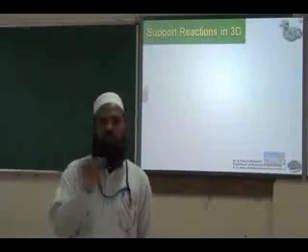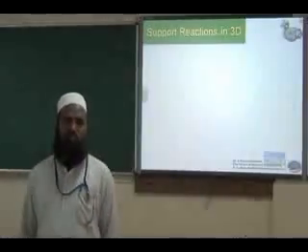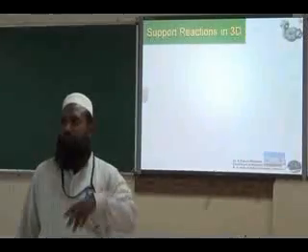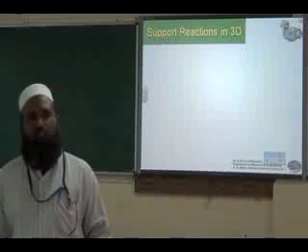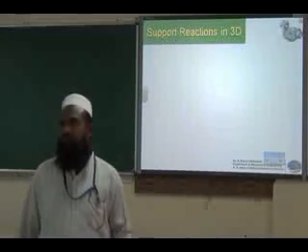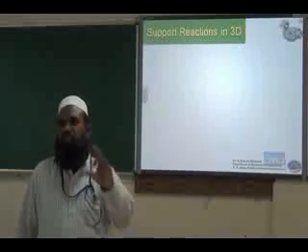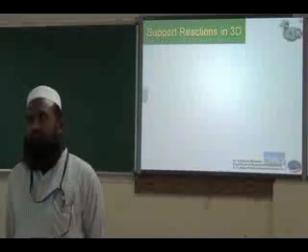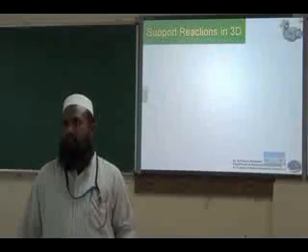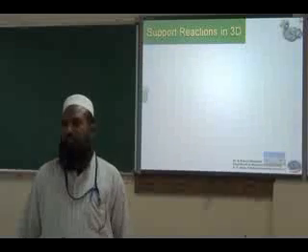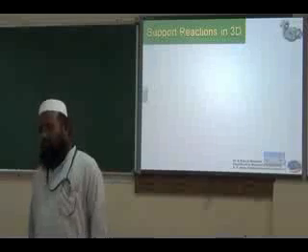If there is no translation, the sigma F will be equal to 0: sigma Fx equal to 0, Fy equal to 0, Fz equal to 0. Similarly, if no rotation, you will have sigma M equal to 0: sigma Mx, sigma My, sigma Mz equal to 0. So the three translations will produce three equilibrium equations, and three rotations will produce three moment equations. We have to apply this for our problems to find out the unknowns.